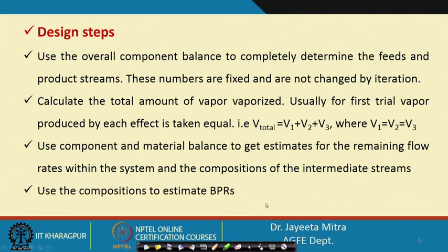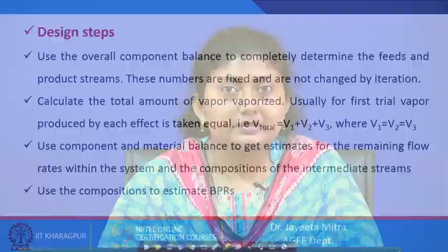And once we get the concentration, we know that concentration has a relation with boiling point rise. Although the biological materials we have seen do not provide a very high boiling point rise, to understand how boiling point elevation affects the operation in a multiple effect evaporator, we will now solve including boiling point rise.